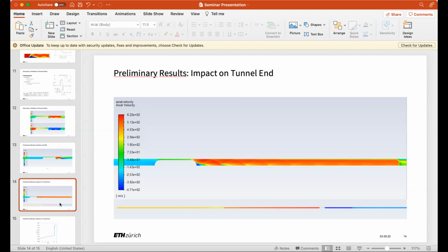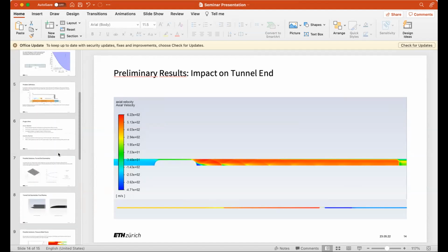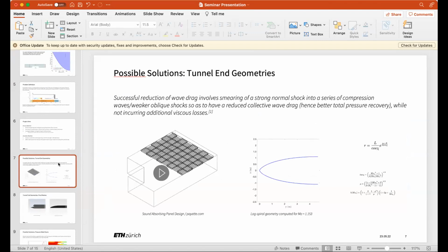Then somebody would like to know, did you compare the shock speed with the piston analogy? Yes, it's something that I'm working on a derivation of, sort of my own math of that, but going by literature, we did find that it is quite close. Actually, our theoretical calculations for this log spiral shape are based on theoretical piston effect calculations, where we found that the leading shock wave speed that we were expecting was about 400 meters per second.